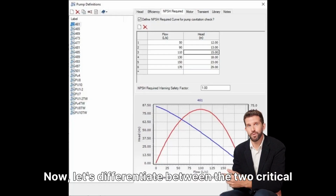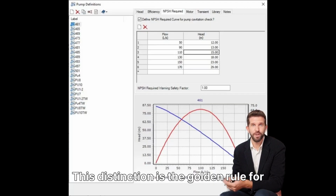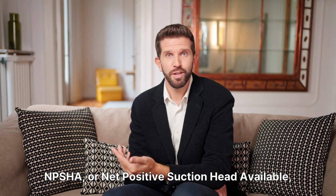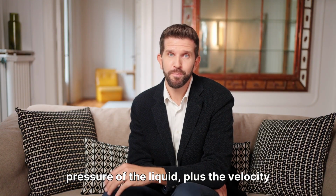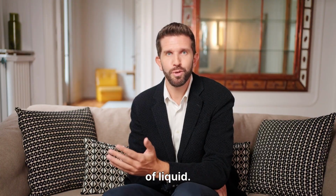Now, let's differentiate between the two critical types of NPSH, NPSHA and NPSHR. This distinction is the golden rule for preventing cavitation. NPSHA, or net positive suction head available, is the absolute pressure at the suction port of the pump, minus the vapor pressure of the liquid, plus the velocity head, all expressed in feet or meters of liquid. It's what your system provides to the pump.